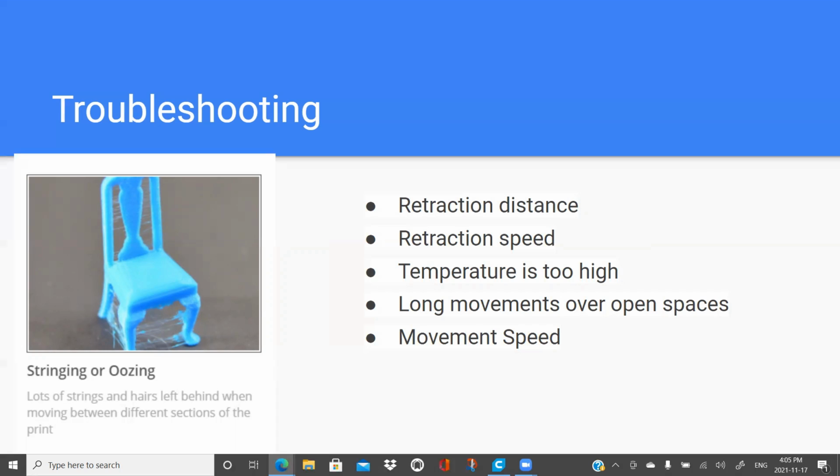So usually we have a sweet spot for retraction speed. It's between 1,200 to 6,000 millimeters per minute, or 20 to 100 millimeters per second. And that's where you're probably going to see retraction performing the best. And most printers should have that set as their default.